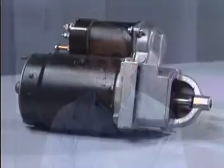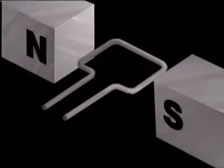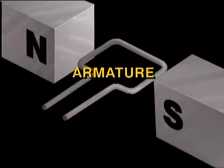Magnetic push from stronger field to weaker field is used to create movement in an electric motor. Let's see how the motor is designed to convert magnetic push into a rotary motion. An electric motor is designed to take advantage of magnetic push. The conductor inside the motor is bent into the shape of a U. It's connected to a pivoting base that allows the conductor to spin between the two magnets. This conductor is called an armature.